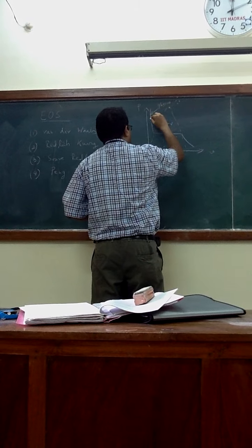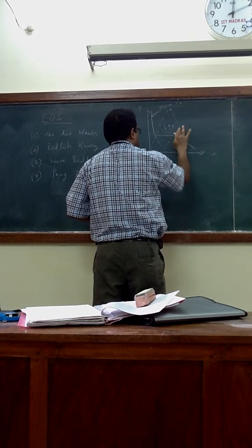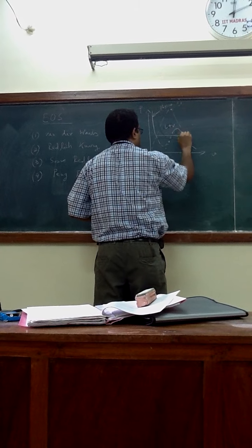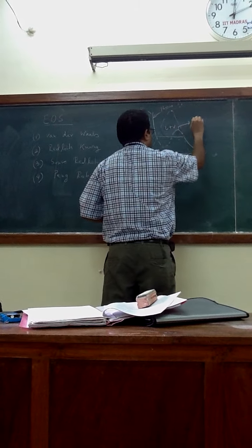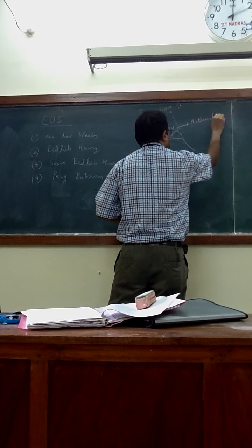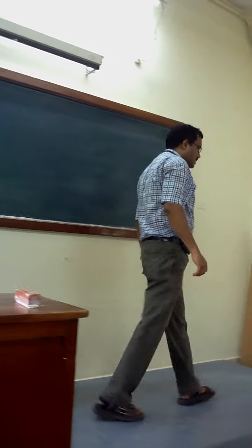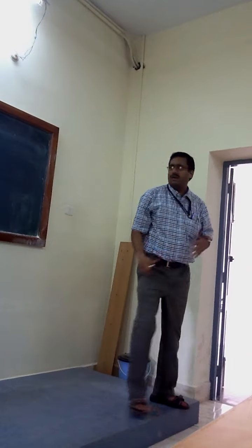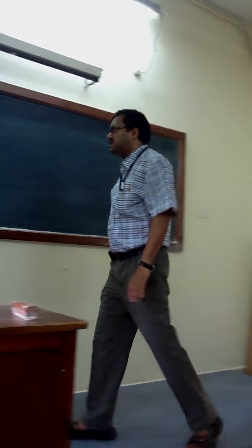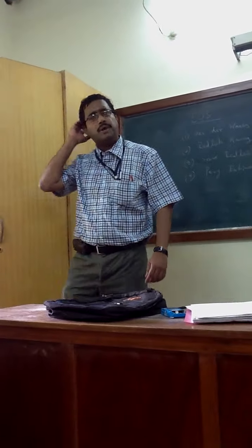And from mathematics, one can actually have the solution like this. This dotted line is from mathematics, and this solution will change depending on the equation of state you select, like van der Waals, Redlich-Kwong, and Peng-Robinson.